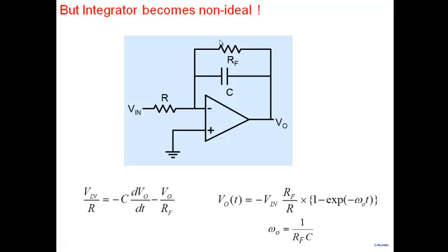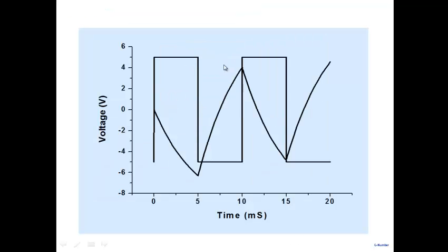It allows a path for the bias current to flow. It provides a path for the DC current due to offset voltage to flow here, and sort of keeps these effects under control. It keeps the voltage resulting from bias current and offset voltage small, so that this equation is reasonably valid. So the whole idea of putting an RF is to minimize the impact of offset voltage and bias currents here. So you have to design it like that. You have to choose RF to minimize those effects.